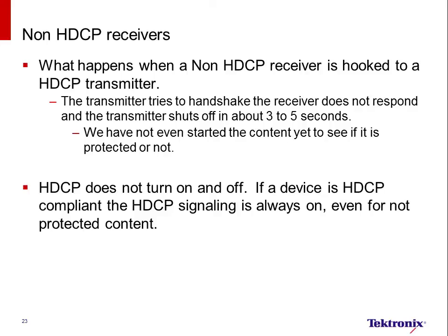That's the issue we've got in the broadcast community when we're trying to deal with looking at or taking HDMI devices and actually convert it over to SDI. HDCP keeps getting in the way all of the time. And we need to know about this and know how to handle it and what to do when this happens. And what to do is basically not a lot. If the device puts out HDCP, you're not supposed to break it.